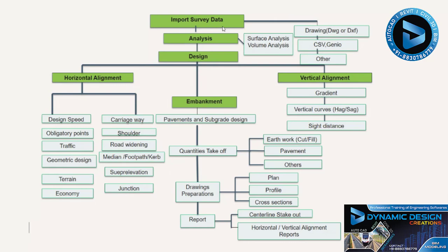Once imported into Civil 3D, we need to segregate the data. The ground points and the electrical pole points are segregated with the help of Civil 3D. Once the data is segregated, we create the surface. Surveyors generally give different forms of files. Some people give contour elevation files, some give point files, and some give 3D polylines. Based on that, we can create the surface.